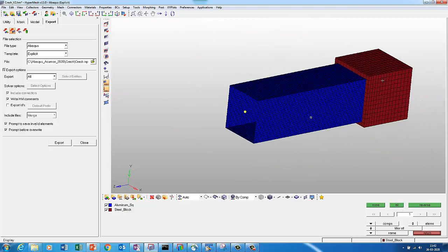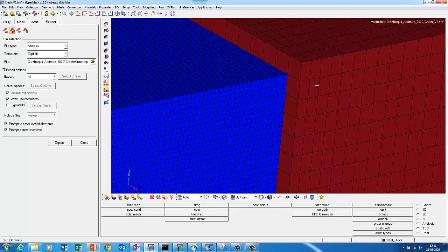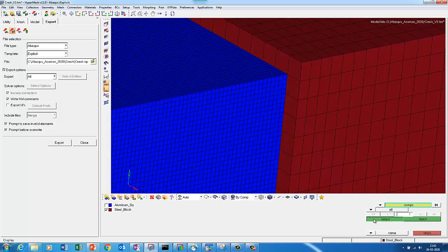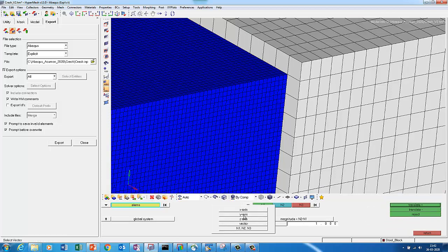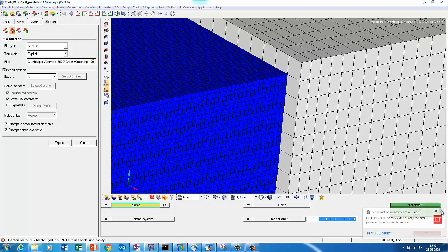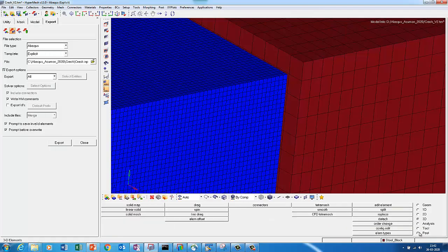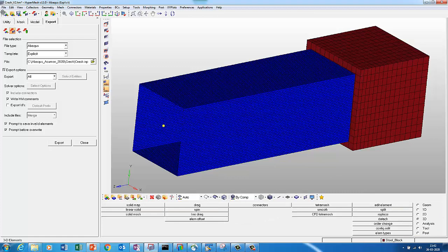It is just touching my face, so I just want to move a little bit back. So I select it and I say Z direction, I say -1. So I moved it back. So now both components are made, both are positioned now.